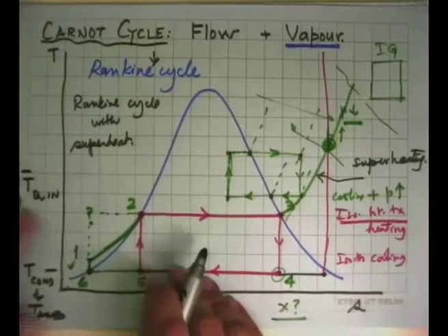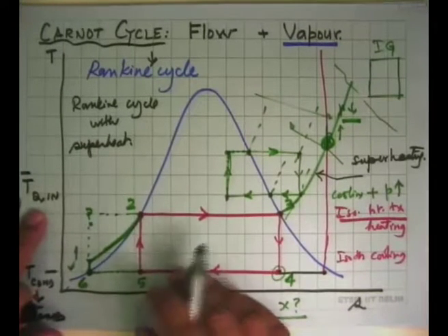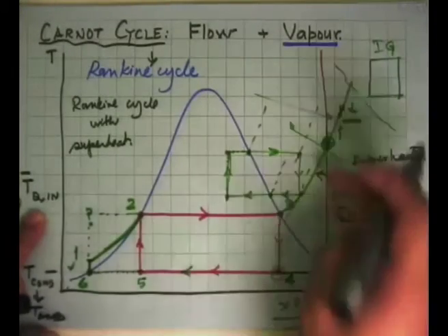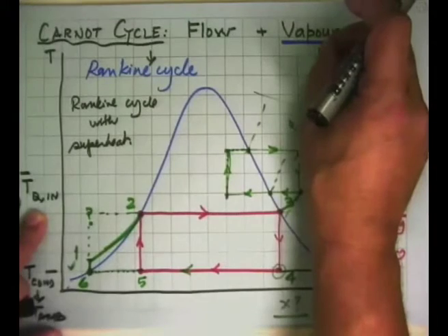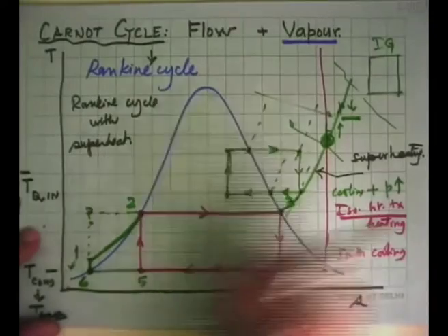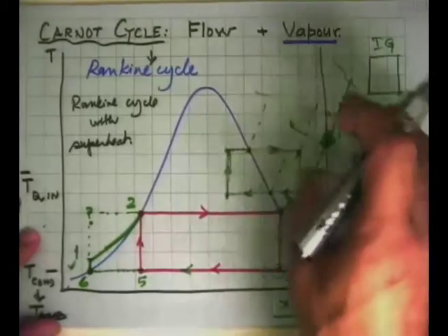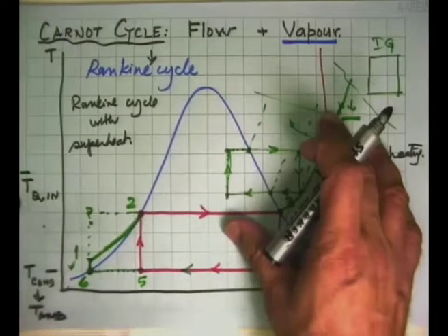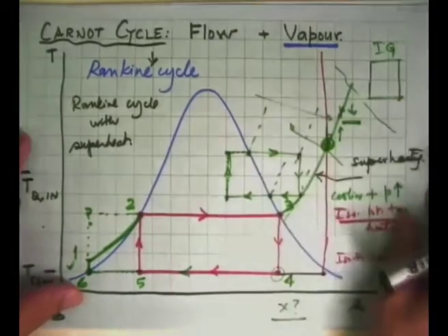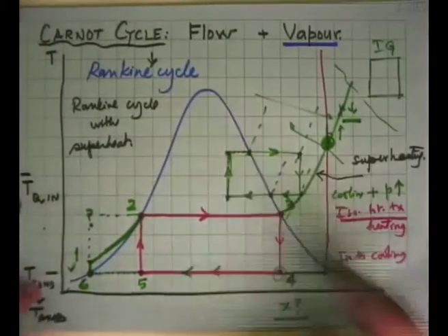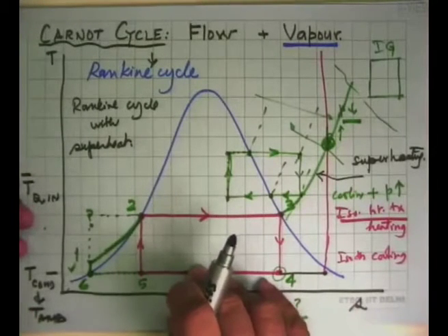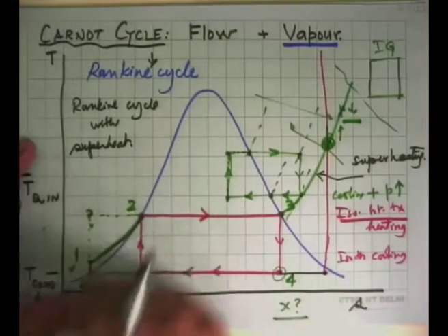The idea is, how can I increase the average temperature at which we add heat? So everything we want to do is to take this point as high as possible. And this very simple fact becomes the basis of doing all R&D related to not just steam power plants, but also gas turbines, aviation turbines, everything. So what we see happening in the real world as greater and greater efficiencies happened because of this very fundamental motivation that comes from very simple thermodynamics that we are now learning. That's the far-reaching implication of what we do.